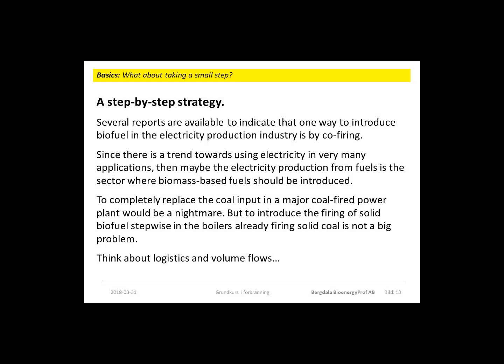Since coal-fired power stations may well have thermal powers of several thousand megawatts, it is not realistic to just switch to biomass, but co-firing is always one realistic way to go. Some people would argue that the biomass first must be torrefied. Others argue that pellets can be milled together with the coal. Torrefied material has advantages from a storage point of view, but non-torrefied pellets are cheaper.